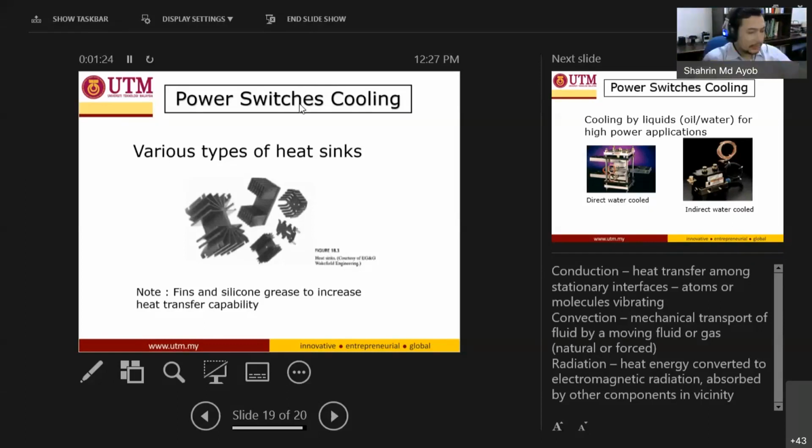And this is also another inverter circuit, with a different kind of heatsink. This one is much steadier and sturdier compared to the other one. The size of the heatsink will determine the compactness of your system. That's why there is research and calculation on how to determine the suitable heatsink size, so that the temperature of the transistor will remain optimum.